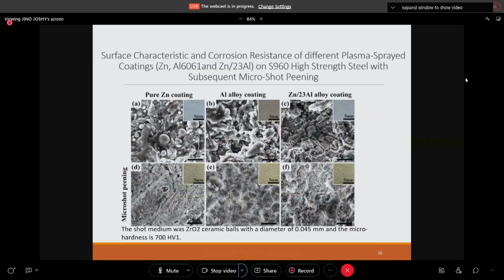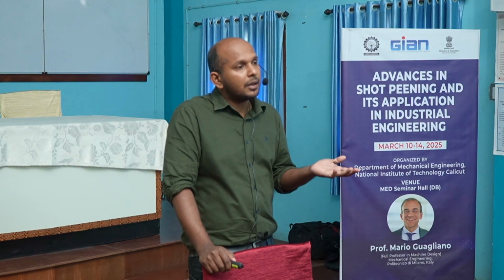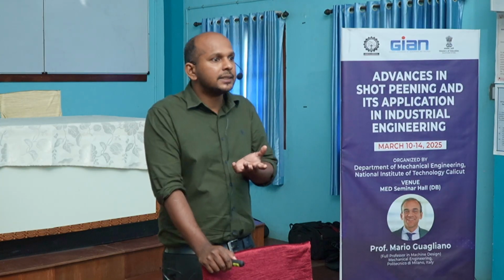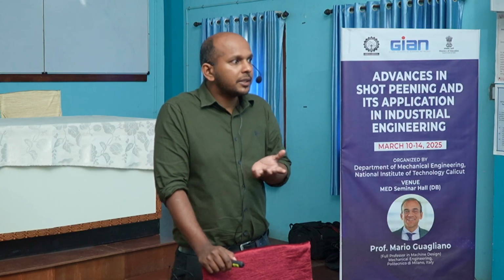Again, we should not limit ourselves to the shot peening operation. We can take the sample and do laser surface texturing. Also, we can go for sandblasting; multiple methods we can go for, and we can check how these pre-treatments affect the final coating property. Also, once we did a coating, the same methods we can go for as a post-treatment. Once we did a coating, we can do some laser surface hardening, or we can do sandblasting of the coating layer.